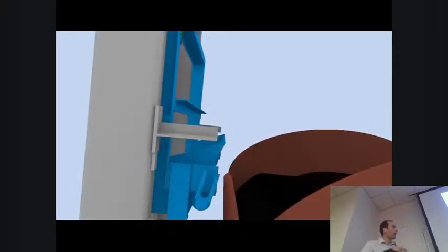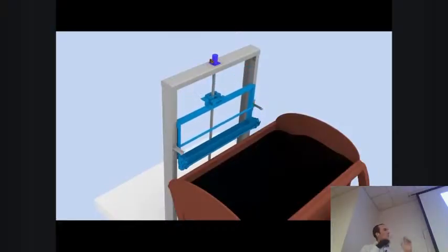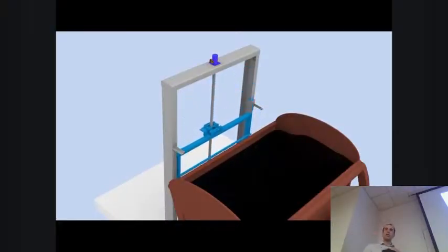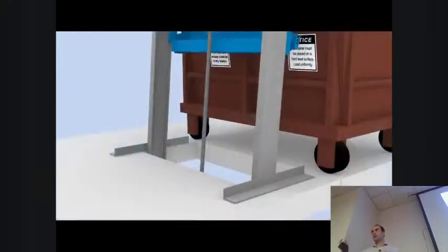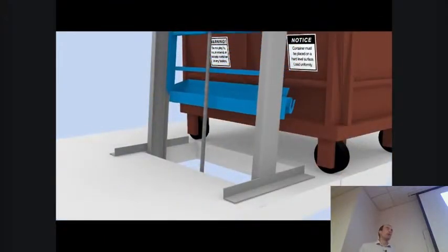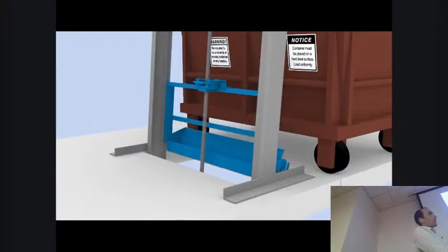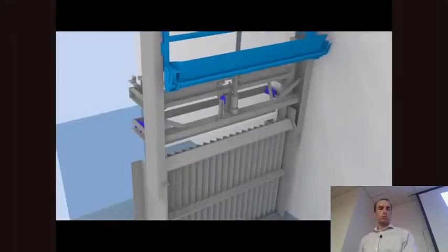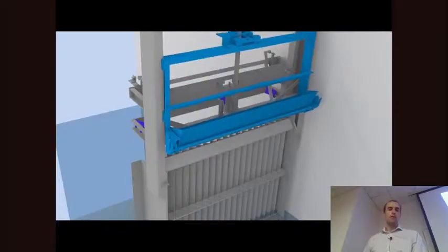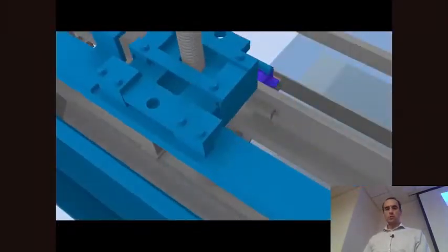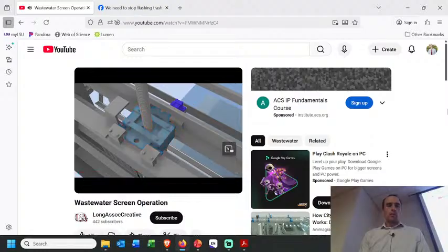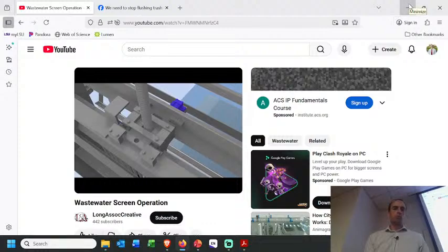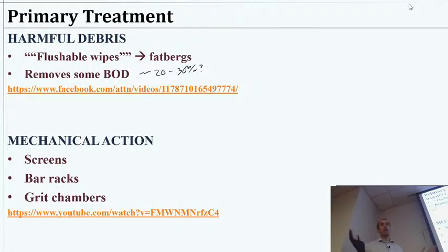From here, maybe we go through one more step. They have little barrel tumblers, almost like a dryer, where water can go through and it'll collect large sand or tiny pebble size stuff. Those types of steps are really nice to help prevent any damage to plumbing and the pumps that the water will go through next. So all these pieces are pretty important, even if they don't do anything super fancy. Of course, after these grit chambers or screening, then we'll go into the first clarifier, the first sedimentation basin, let gravity do what it can, and move on from there.